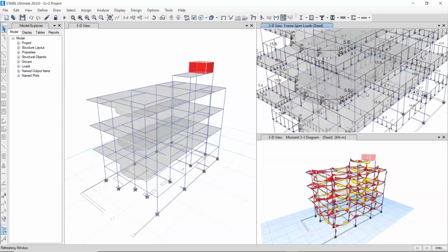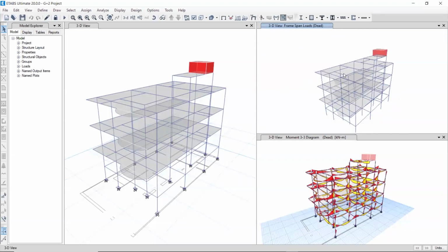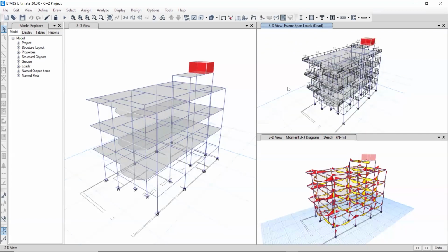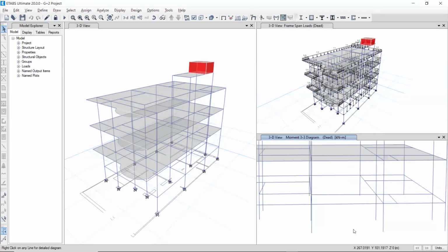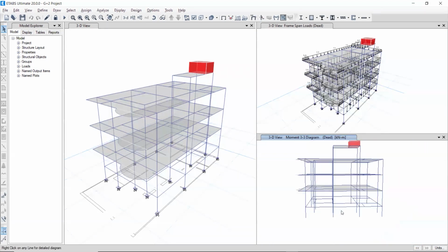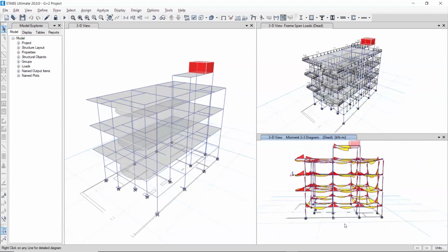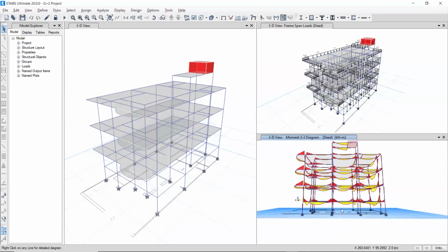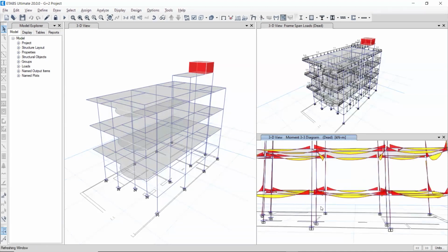Okay, so you can see the entire loading of the balcony, beams and slabs. The entire loading we have done in this course. After this loading is done, you can go for the analysis in this software. What loads and what values they are going to get, what forces they are going to get, you can learn in this Etabs software. Here you can see, it is very clear, this is a continuous beam which is getting a hogging moment at the support. You can see the right part of it, the support part, hogging moment, and the sagging moment at the bottom of it.